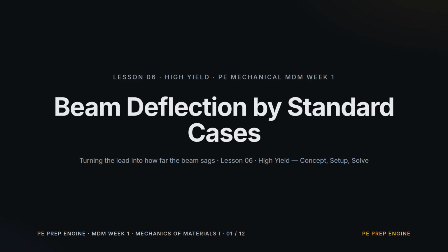Lesson 6. Beam deflection. Last lesson we had both beam stresses. Now we ask how far the beam actually sags under load. On the exam you almost never integrate the elastic curve. You match the support and the load to a standard case and read off the maximum deflection.